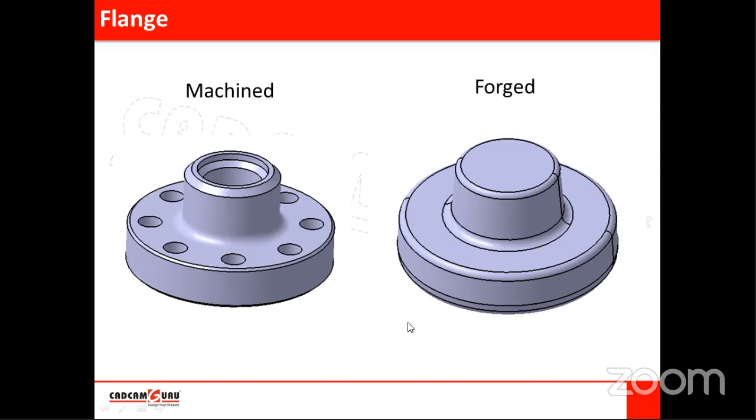On this, where there is machining, we have to add machining allowance. Then decide the parting line. Here we need a parting line, which means this is the maximum material area, and we place this parting line at the half location, or less than half. If this thickness is 50 mm, then you can locate it at 25 from this bottom, right? So this is the parting line.